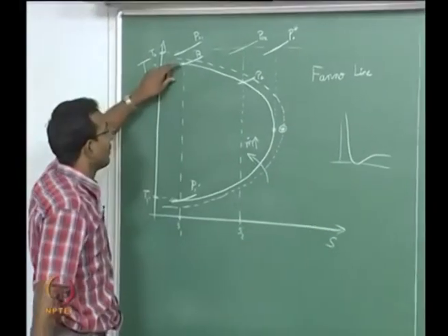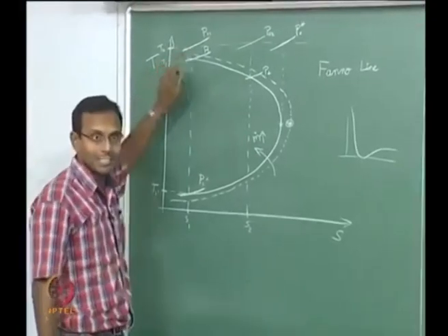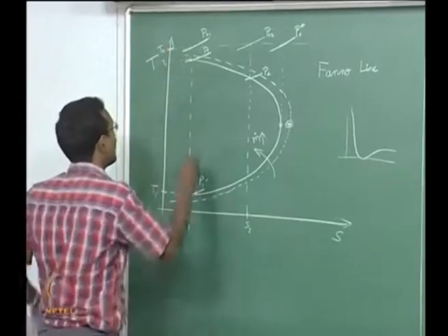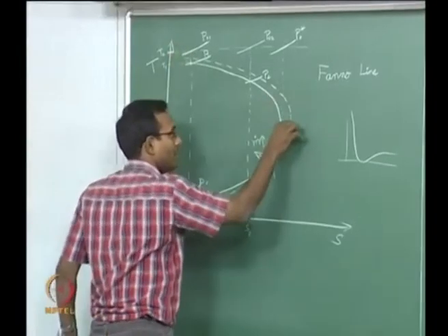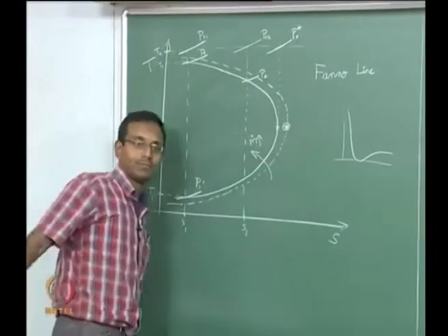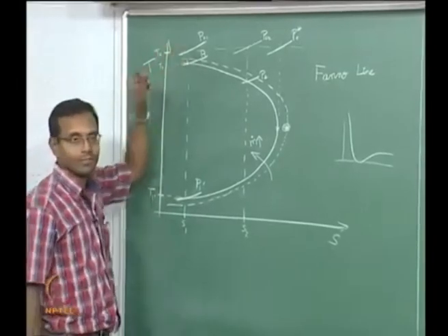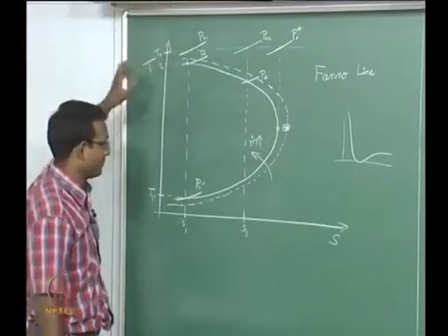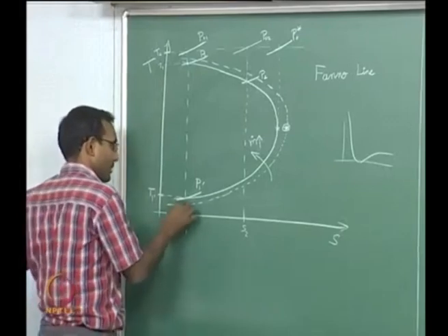So I go to a lower Mach number as starting point. Now my L star is higher. That is the reason why the flow wants to do this. Okay, it has gone there. So now it chooses some particular curve such that it will come and make it just L star at that point. So it will go on choosing till that point. It will not go any further above. That is the idea here. And similarly, if I go to supersonic, it can do that.